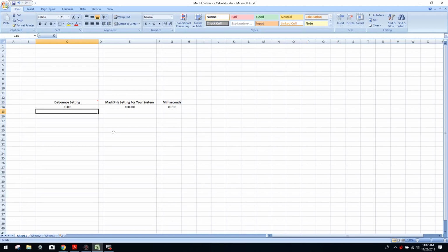I don't recommend normally grounding both ends on any shield. Again, because there are certain systems that can induce a ground loop, and it may not be noticeable until you guys actually implement it. That's why I say start with the basics and work from there. Always work from the base of the problem and then work out. It's like that old school fishbone theory, just expand out. Start from the spine, expand out. Same principle here.